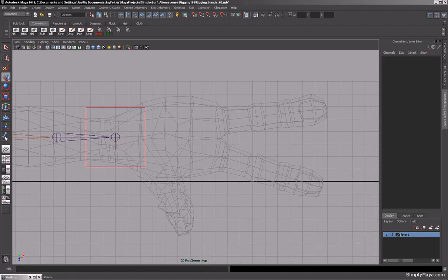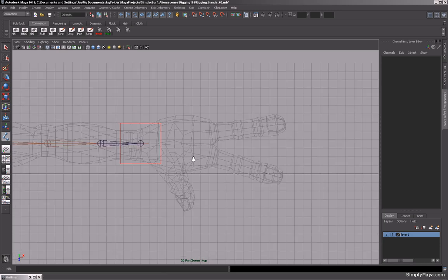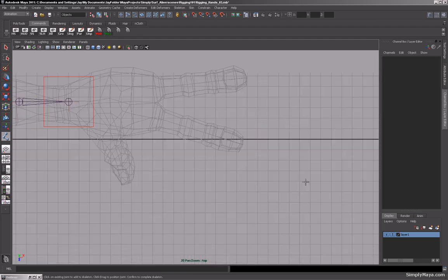So what we're going to do is, what we could do is click on this to complete the chain link as we go. But because we've got orientations and point constraints, it does sometimes make it a little bit difficult, and this does flip out. So we're going to start our first joint here, and then bring it all the way around and into the index finger around there. Then we'll move everything up into position, and parent that all back up, and we should be good to go. And by doing it this way, you can also mirror the joints across for the right hand side as well. So we'll kill two birds with one stone in this particular exercise.